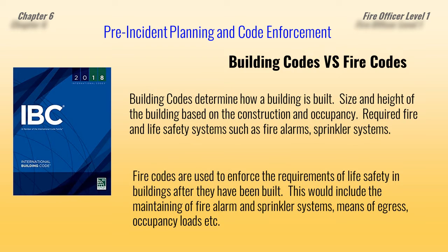Fire codes, on the other hand, are used to enforce the requirements of life safety in buildings after the building has been built. So this would include the maintenance of fire alarm systems, sprinkler systems, exits, which we call means of egress, occupancy loads, that type of thing.